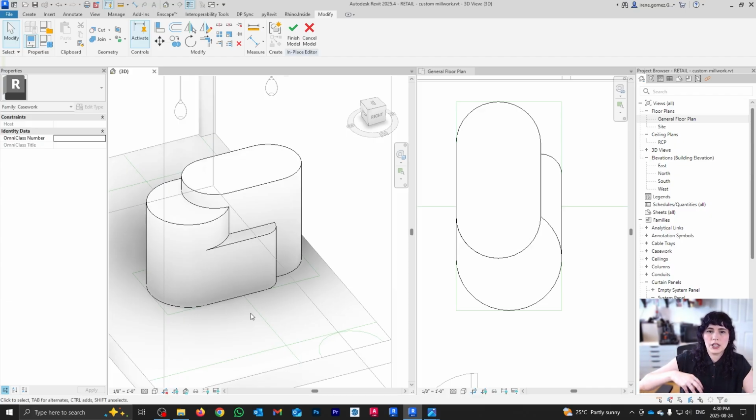One option would be that you edit the actual geometry. So I go into the profile of this cylinder and I change it. Option 2 would be that you just model these additional elements and then join them the same way that we created these cylinders. I'm going to choose the latter just because it's going to be a little bit easier.